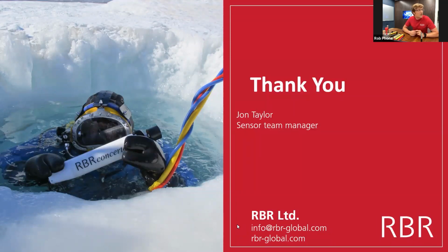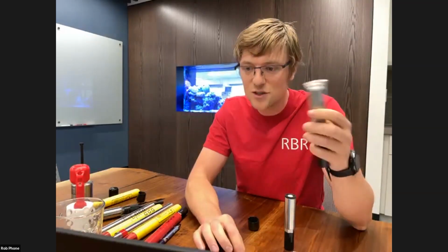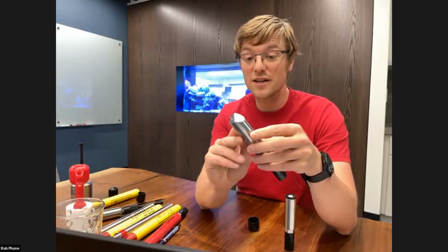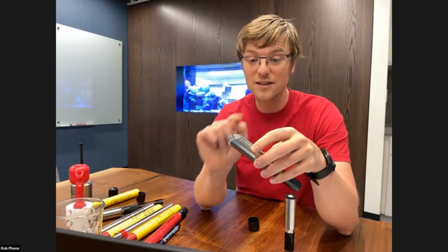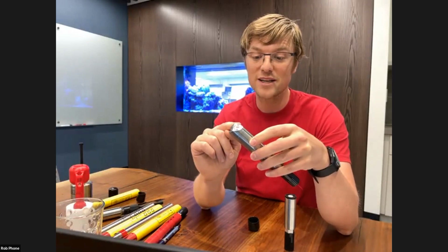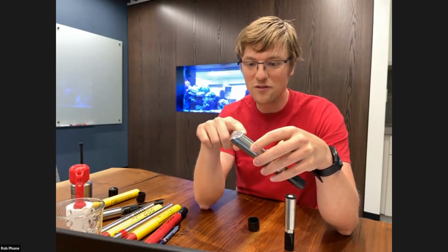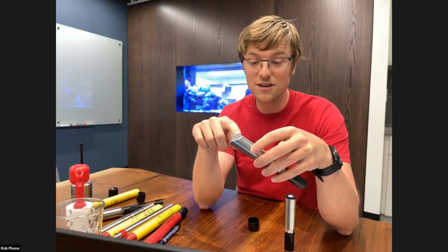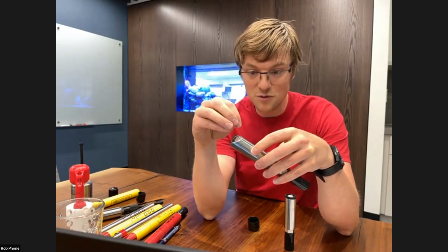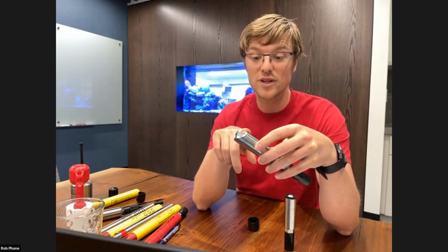So the first question is from Kelsey. Are the optical oxygen sensors putting out a beam of light, or are they relying on ambient light? So yes, I don't think I touched on that. Yes, there is... oh, here, I'll stop sharing so I can show the optode. Inside there is an LED that is shining on the back of this membrane here. We have a piece of glass and then the membrane sitting on top, and the oxygen diffuses from one side, and from the other side, we hit it with an LED.